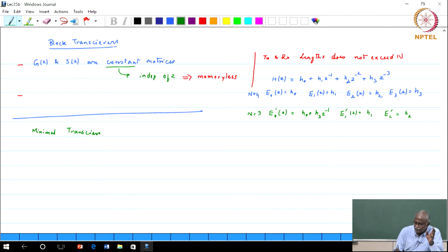One of the simplest, and the one that we have already looked at, is if you choose this G and S to be the IDFT matrix and the DFT matrix, because you can see the polyphase structure. There is a notion of the IDFT and DFT being useful in these types of environments. So, based on the IDFT and the DFT. Very important, these are square matrices.